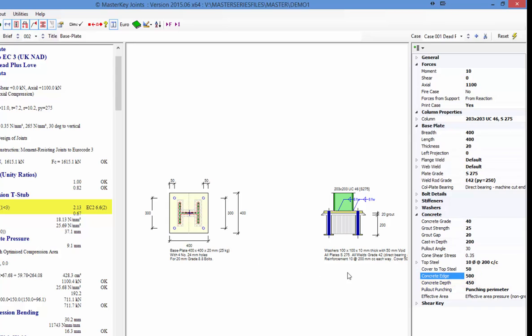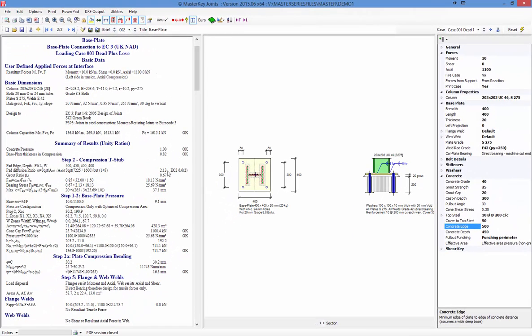And that is, as I move down, move that up from 1.5 to a far more enhanced 2.13. So that's a way of getting a far higher compression capacity on the concrete. That pulls the whole compression zone back in again, and therefore allows the maximum thickness or cantilever to be 31, so we actually can end up with a thinner plate. So we can actually come down.